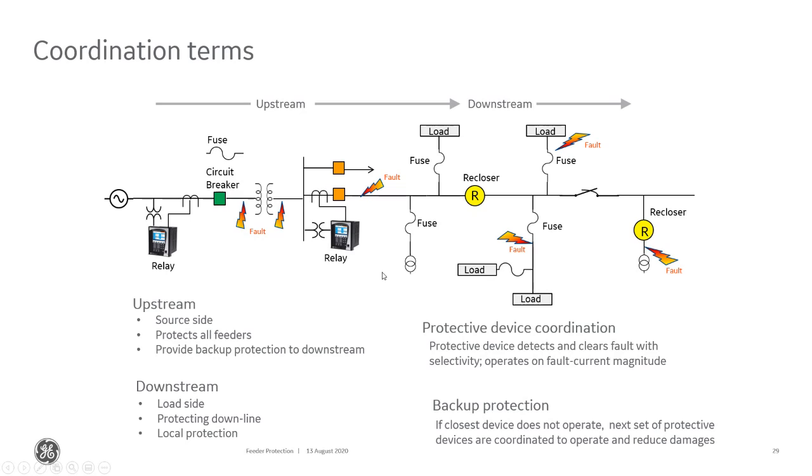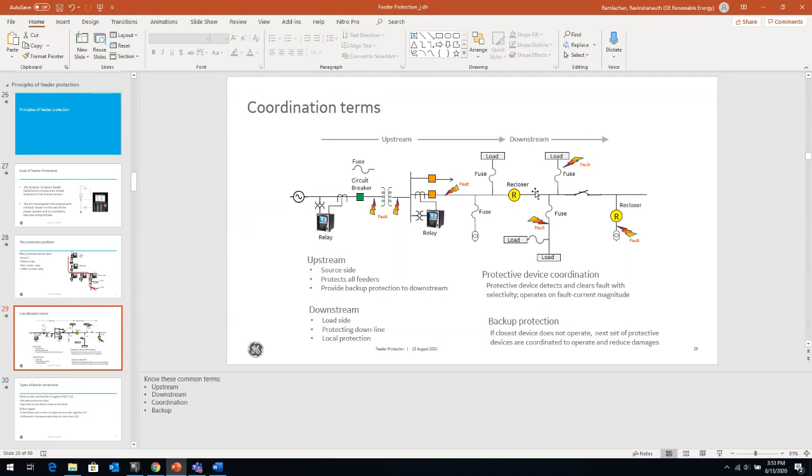So we had to develop some special logic, and this is where microprocessor relays help a lot. We had to develop a special logic so the relay switches to a slow speed curve when it sees the auto recloser operate and reclose back in. So that's a very special situation. I think I kind of beat around the bush with that question a bit, but the bottom line is I've seen the high speed on transmission, not so much in distribution, auto reclosing.